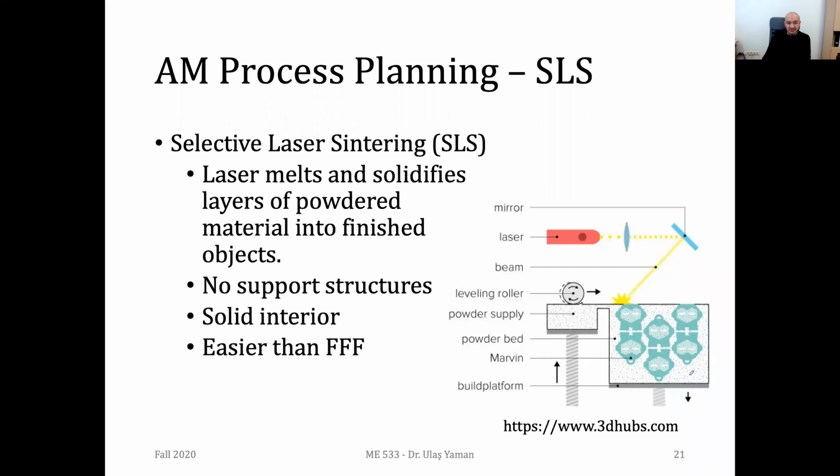And another difference with respect to fused filament fabrication is that you don't need to be concerned about various infill patterns or infill percentage. For every part, you'll have a solid interior. So the interior of the part should be sintered 100%. You shouldn't have any gap, any, let's say, void inside the part.